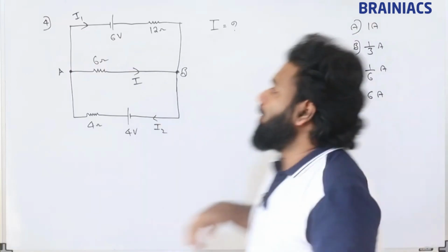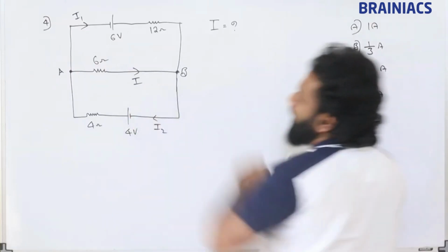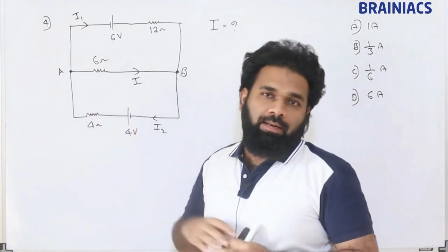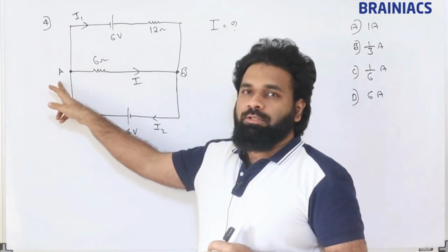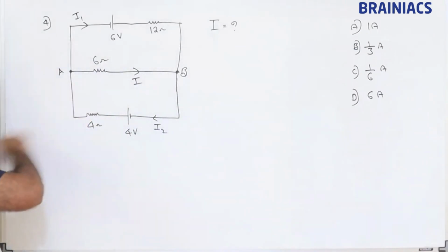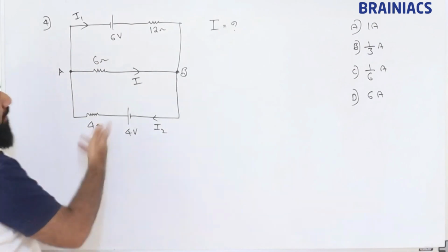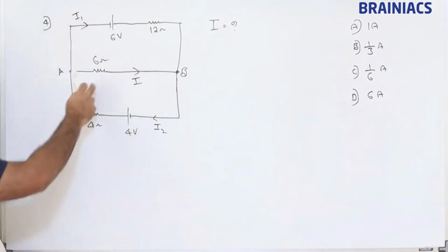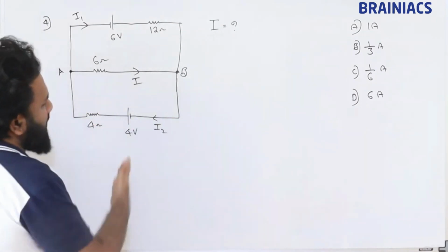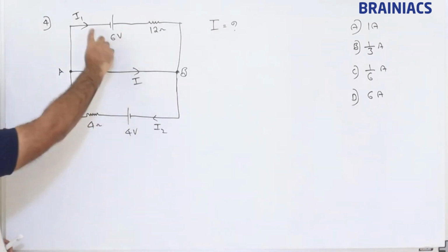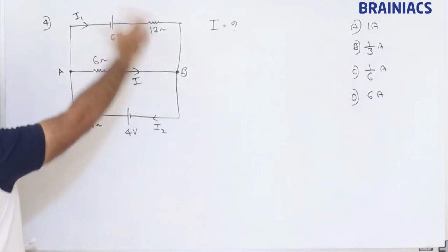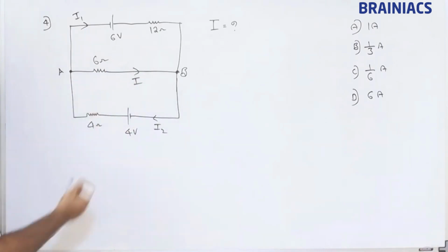Take a question. We just need to find the value of current. Now what is the value of current through 6 ohm? We can do this using nodal analysis also. If we find the node voltage at terminal A, then that voltage divided by the 6 ohm will give the current. You can try that method, just practice nodal analysis also for this question. Since we are studying the parallel combination, I am going to use that concept to solve this question. This cell and internal resistance, and this cell and internal resistance, are connected in parallel with one external circuit.